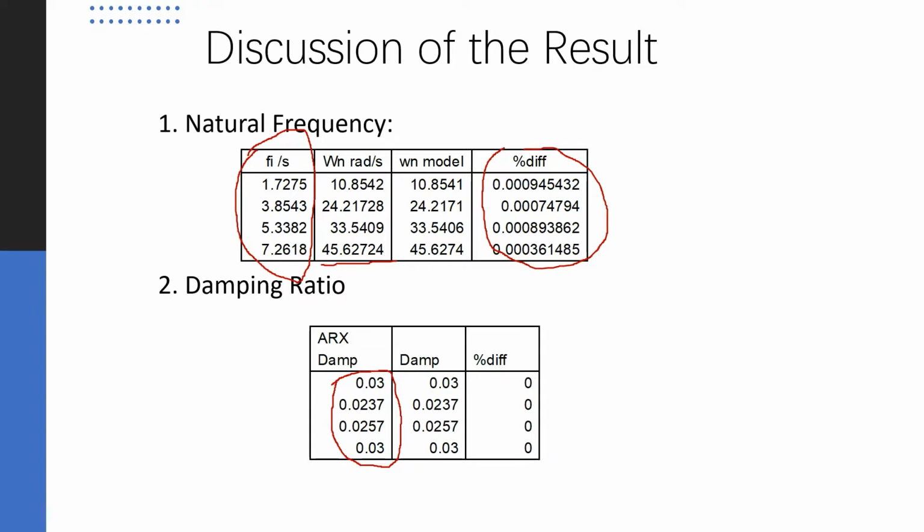So we can use a sorting function to get everything in order. However, this is under the condition that there will be only 4 natural frequencies coming out from MATLAB. We assume that there are 8 poles, 4 conjugate roots of the transfer function, so we only get 8 poles. And the number of poles divided by 2 is exactly the total number of degrees of freedom.